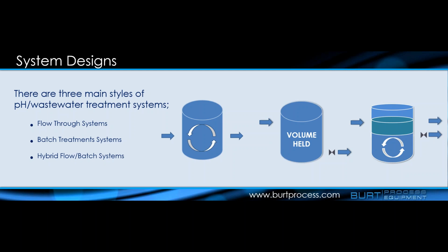In a lot of industries, pharmaceuticals, semiconductors, even manufacturing, they tend to have more extreme waste conditions than you would see in a laboratory or academic environment. People often go with what's referred to as a hybrid flow system. This offers both the advantages of a flow-through style system while still having the built-in ability to go into a batch mode temporarily, either within the treatment system itself or by using an equalization or specification tank.